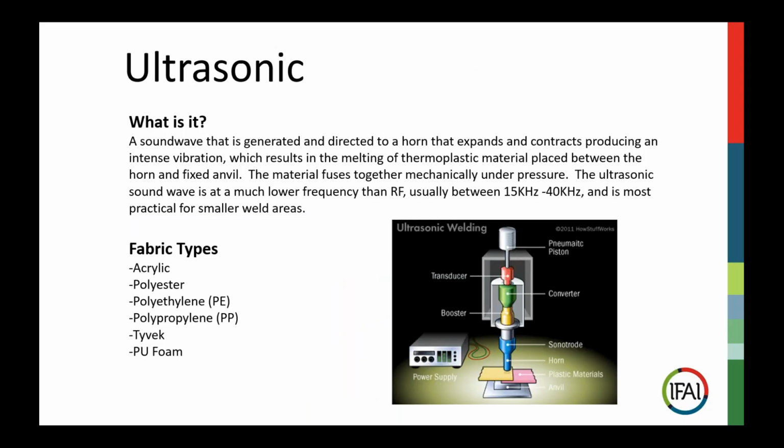So let's move on to the other technology that I'm going to talk about, and that is ultrasonic. Many people think that ultrasonic and RF are the same thing, that it's interchangeable. I hear this a lot. And actually, they're not. Ultrasonic is basically a sound wave at a high frequency, but much lower than RF. It's only about 15 kilohertz to 40 kilohertz rather than the 27 megahertz that I mentioned earlier.